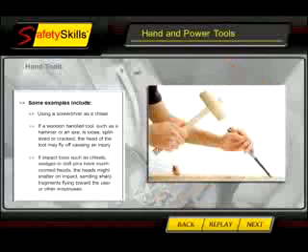If impact tools, such as chisels, wedges, or drift pins, have mushroomed heads, the heads might shatter on impact, sending sharp fragments flying toward the user or other employees.